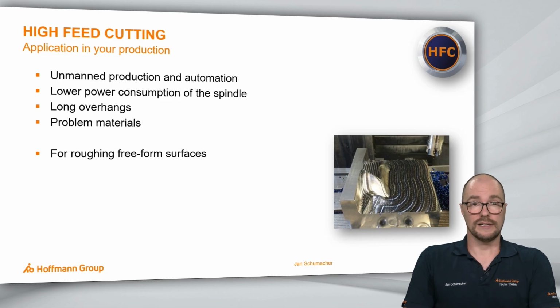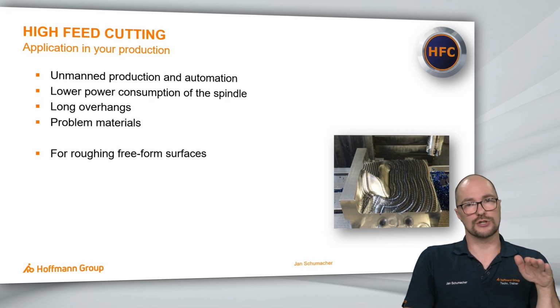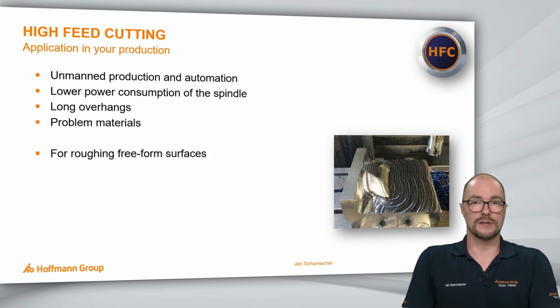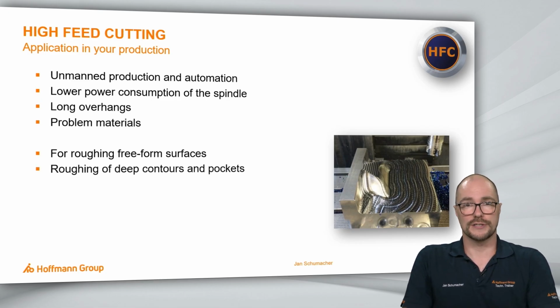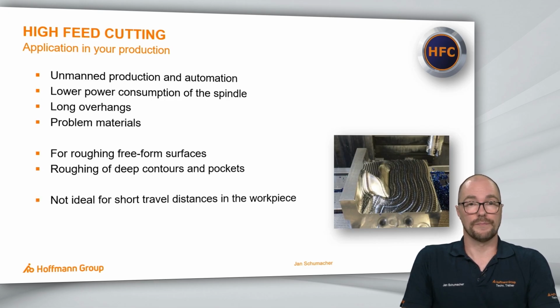Particularly suitable is the HFC strategy when it comes to machining free-form surfaces, like we can see here on the right, because your very small depth increments already bring you very close to the finished surface, so you can get rid of some pre-finishing or post-roughing operations. And it's also particularly suitable when it comes to deep contours and pockets.